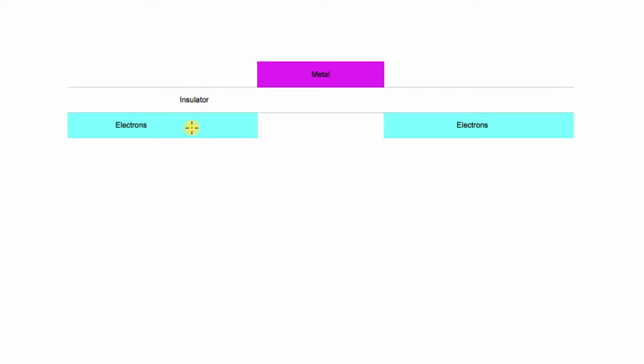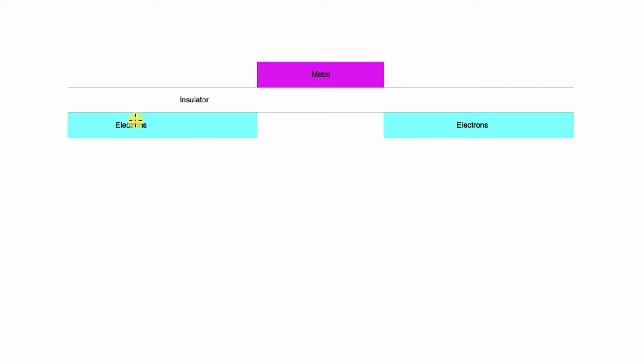But when we put the atoms into this region, which donate their electrons, those atoms each had an extra proton down in the nucleus because they were neutral atoms when you put them in. So these regions that have all these free electrons that can flow around also have a lot of positive charge from those atoms that donated their electrons.